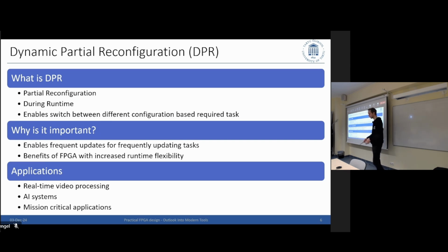In cloud computing and in other domains, you have trends emerging, and in space also, that you start reconfiguring, because it gives you just so much potential to change your logic later on in the mission. You can reconfigure or partially reconfigure your FPGA, which in this case, just to stick to the newest trend, means that you can do this during runtime.